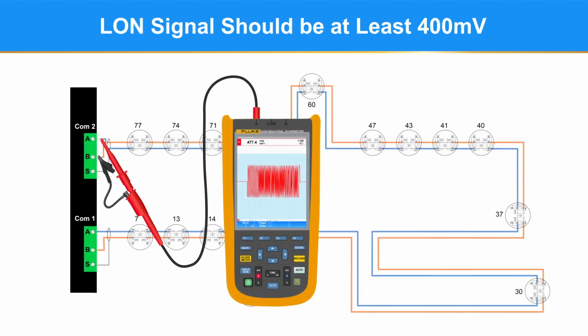It is difficult to see if attenuation is the cause of the loss of the heartbeat without specialized equipment like an oscilloscope. If you do have an oscilloscope, you need to verify the communication signals are at least 400 millivolts in amplitude. If the signal is above 400 millivolts at each controller COM port, attenuation is not your problem.